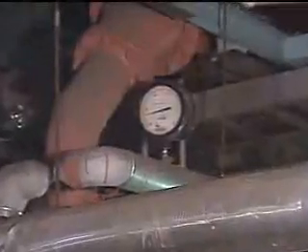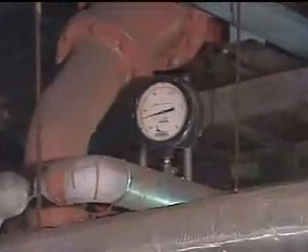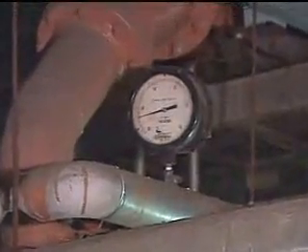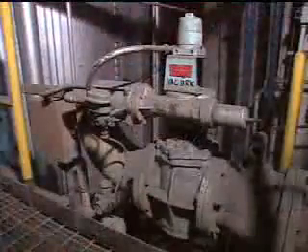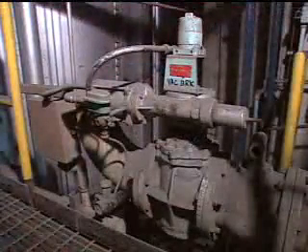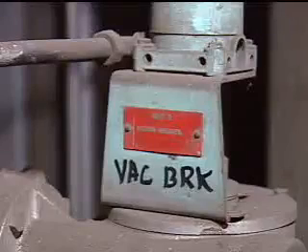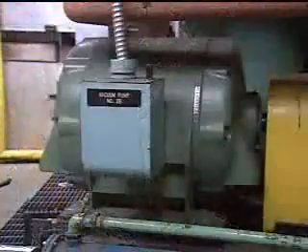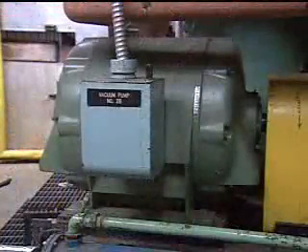Another purpose of the air removal system is to establish a normal vacuum in a condenser prior to turbine startup. When a generating unit is shut down, a vacuum breaker is opened to equalize the pressure inside the condenser with atmospheric pressure. Before startup, the vacuum breaker is closed and the sealing water is opened. Then the air removal system establishes a vacuum in the condenser shell.